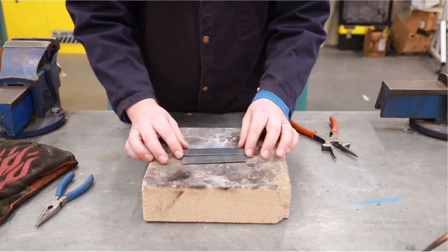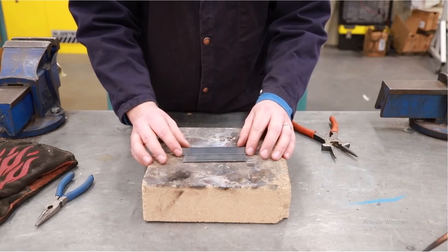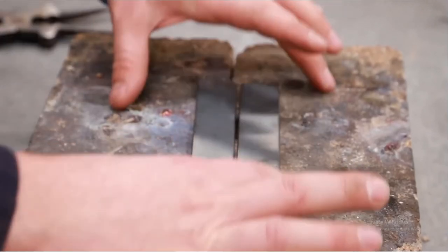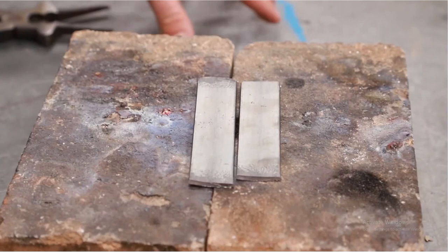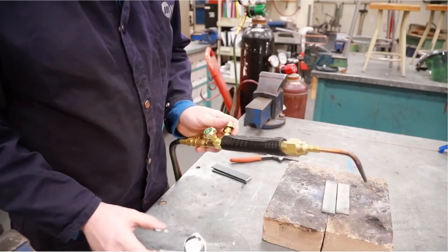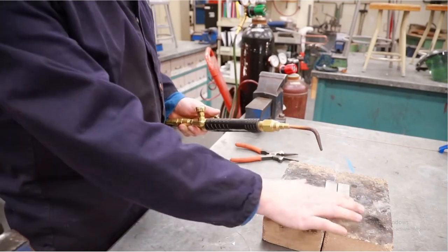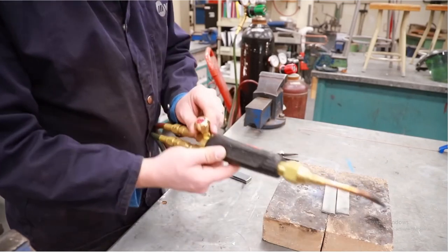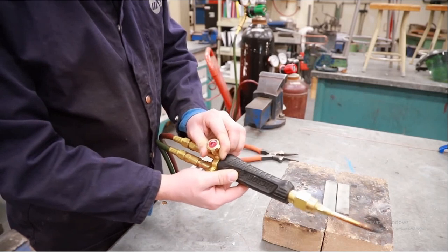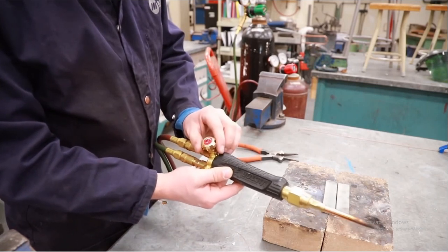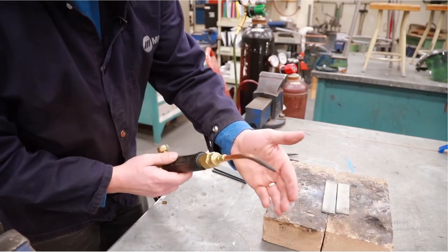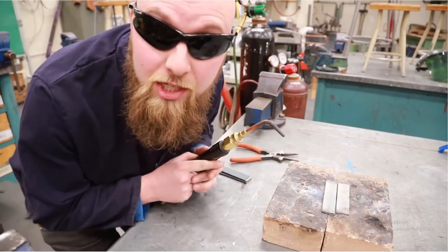I'm going to set up my 2 pieces of flat bar here with a slight gap in between. And I'm using fire brick to prevent my table from getting hot, and fire bricks will not explode when heated. So now that I have my metal set up, I have my torch all ready to go. All I have to do is open my acetylene valve just a little bit, or fuel valve. This one's using acetylene. Open up just enough that you can feel it on your hands, or you can put it up on your ear and actually listen.